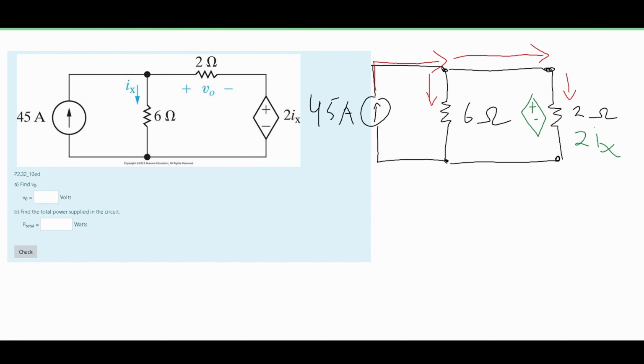So our current is going to be split between these two resistors, which is obviously after we redrew it in parallel. Since they are in parallel, we also know that there is only going to be one total voltage because the voltage across everything is the same. To start, we're going to have to find a current because we're given resistors. So the most obvious thing would be to find the current since we don't know that, and through having our current and resistors, we can find the voltage.